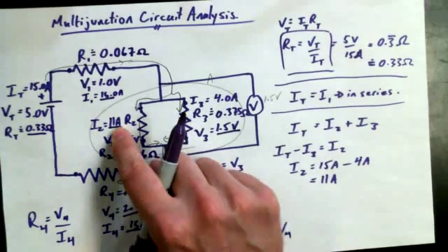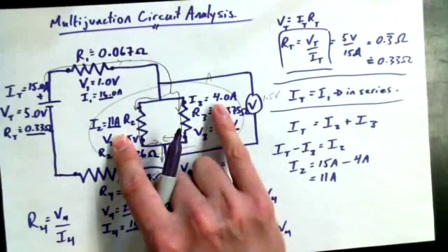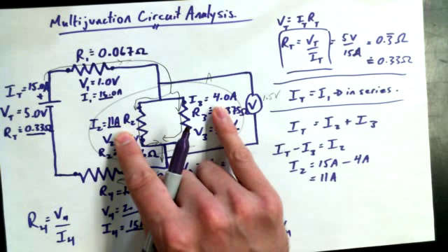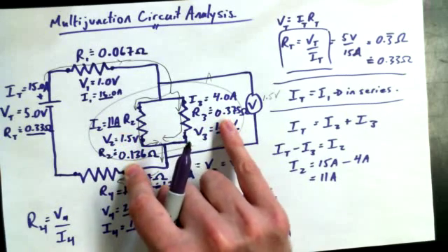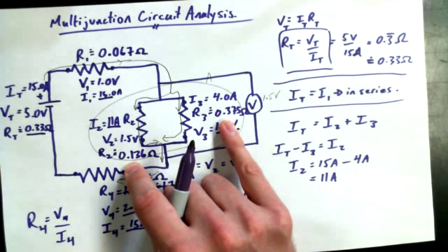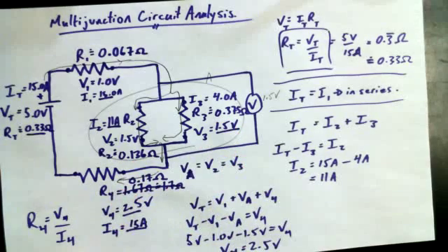I want to look at the current. Which one has more current flowing through? We've got 2 branches. Branch 2 or branch 3? Definitely more current. Now look at the resistances. Let's see if it makes sense. Which one has more resistance? Now if you got more resistance, does it make sense that you'd have less stuff flowing through it? Yes, sir. Why not? So this even makes conceptual sense if you try and compare it to water pipes or something like that. But there's a restricted flow there because of the higher resistance.